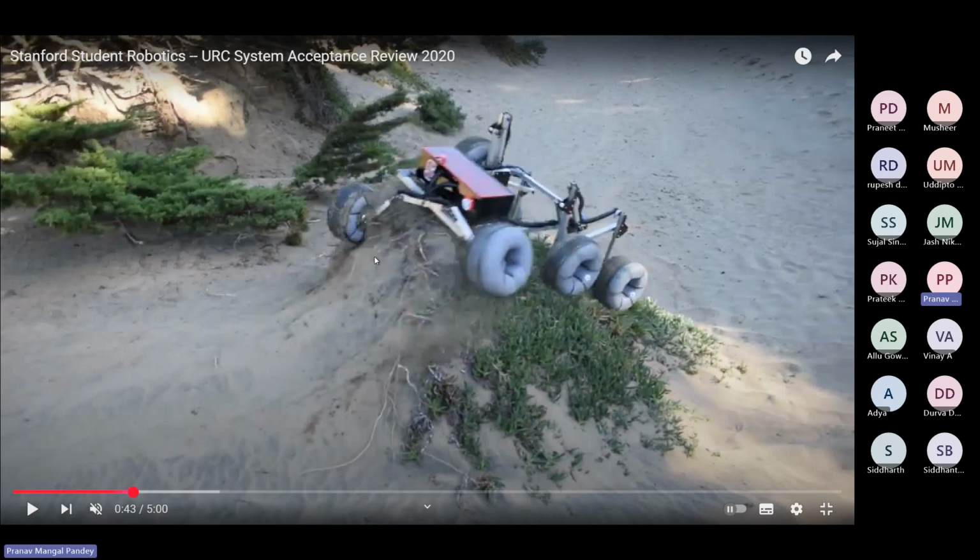Okay, so normally if you are making a suspension system which should work off-track, the normal car suspension has a spring that allows the wheel to go vertically upward or downward. Horizontally it is free to move, unconstrained, but vertically it is constrained. To reduce the shock, we use a spring and allow it to move a little bit vertically up and down.